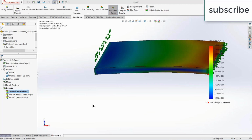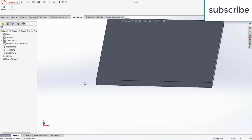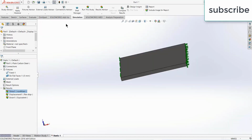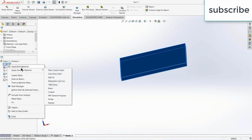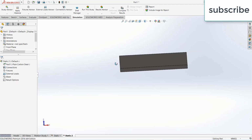Namaste. In this video, I'm going to teach you about advanced fixtures in SolidWorks. So first, let's see our geometry. Here, I just made a simple cuboid. Okay. So let's see what the advanced fixtures in SolidWorks are. Click on new study, click on static, click OK. After that, right click on this, apply the material as per your requirement. I am going to apply plain carbon steel, but you can choose any other material as per your requirement.